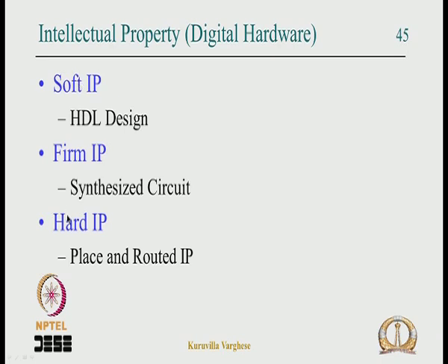There are different types of intellectual property. One is a soft IP. Soft IP would mean suppose you have a memory controller, VHDL or Verilog you can buy and use it. It is very flexible because you can change it depending on the license, but then you have to synthesize it. You have to do the front end design, the back end design. Depending on your tool and the way you design, it may not end up in an optimized design, and it may not give the desired delays, it can be slow. So soft IP is very flexible, but it may not give the performance.